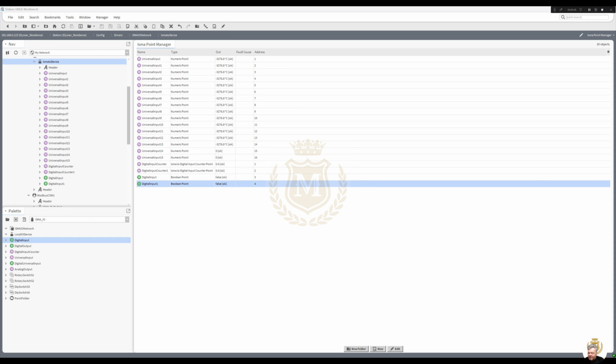Down to the next sheet. So now analog outputs, so that's new, and let's do the 4, which is 4 analog outputs. We're using 1, 2 and 3. Speed control is 1, speed control for pump 5 is 2, and kitchen supply fan heating coil is 3, and 4 is spare. 5, 6, 7 and 8 are all spares.